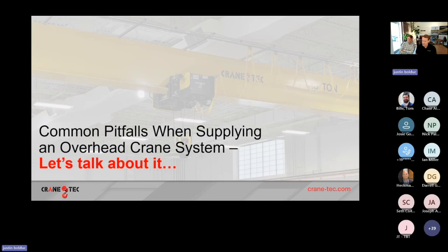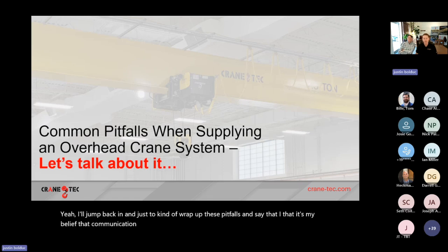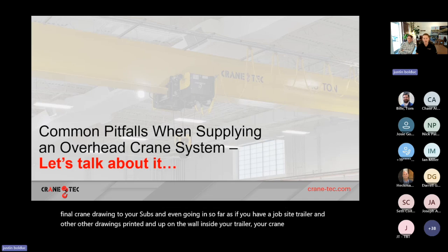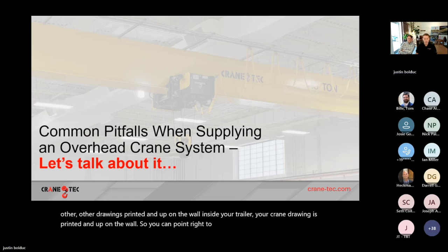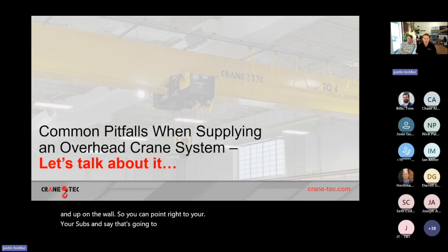I'll jump back in to wrap up these pitfalls and say that it's my belief that communication with your crane supplier and then supplying the approved and final crane drawing to your subs is key. Even go so far as, if you have a job site trailer with other drawings printed and up on the wall, have your crane drawing printed and up on the wall, so you can point right to your subs and say, it's not here yet, but that's going to be here, and you can't get anything in the way of that crane. I'm just trying to communicate to the subs, whether it's a radiant heater or overhead doors, letting them know.